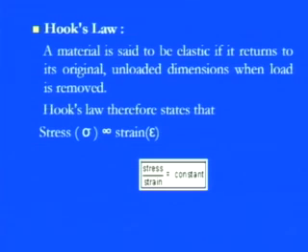When the load is removed, we cannot visualize that the deformation was there when it was loading. We can say that this is the elastic deformation. And Hooke's law, again this is a must condition, is only valid when there is elastic deformation under any kind of loading, tensile, compressive, shear, whatever the loading is. Hooke's law is only valid when the material is subjected to elastic deformation. Then what is the statement of Hooke's law?